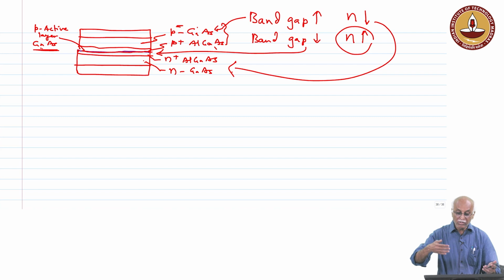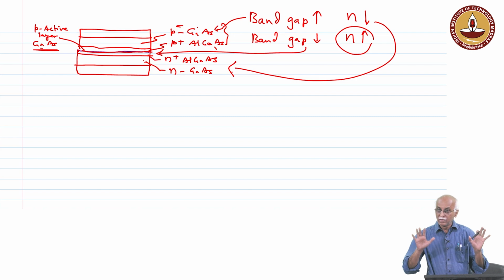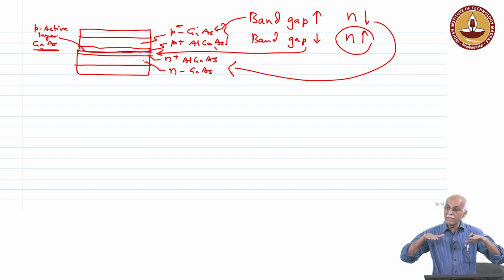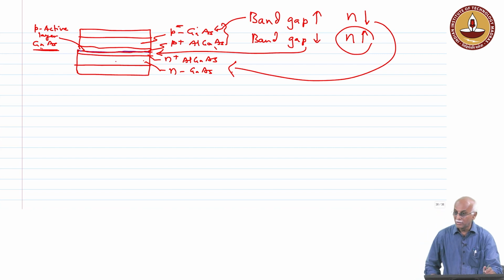Because the refractive index is slightly higher than the adjacent layers, while dopant characteristics and everything else are almost similar, except that the band gap is slightly lesser, which makes that layer a core and the nearby layers the clad, and the light remains waveguided within that small region.